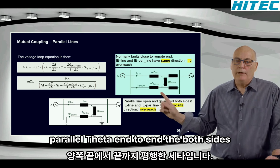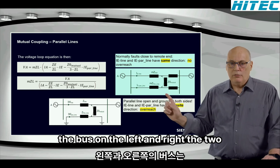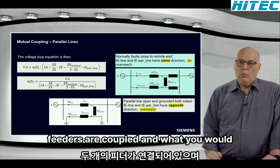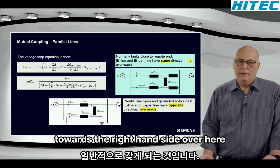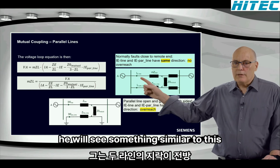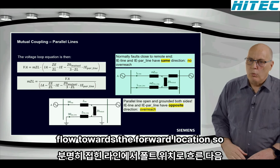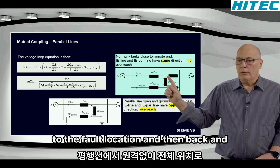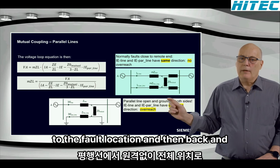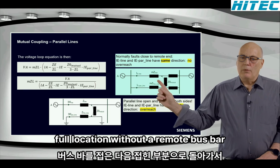The diagram we see here is typically used for the explanation. It's the parallel feeder end to end. Both sides, the bus bar on the left and right, the two feeders are coupled. And what you would then have typically, if you have a fault towards the right-hand side over here, is that the ground fault current on both lines will flow towards the fault location. Obviously on the faulted line, it'll flow to the fault location and then back. And on the parallel line, it'll flow towards the fault location via the remote bus bar and then back to the fault.